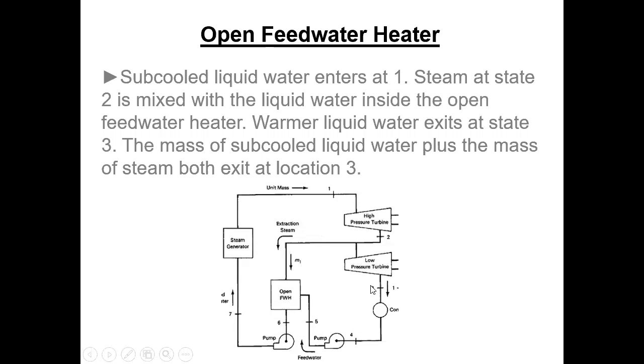Here is our condenser, so this is the low pressure steam. We condense it, say, with lake water. It's maybe 100, 110 degrees. We pump it into this open heater, and we dump a bunch of steam in there, and basically we heat it up. And so what pressure theoretically would this open feedwater heater operate at?